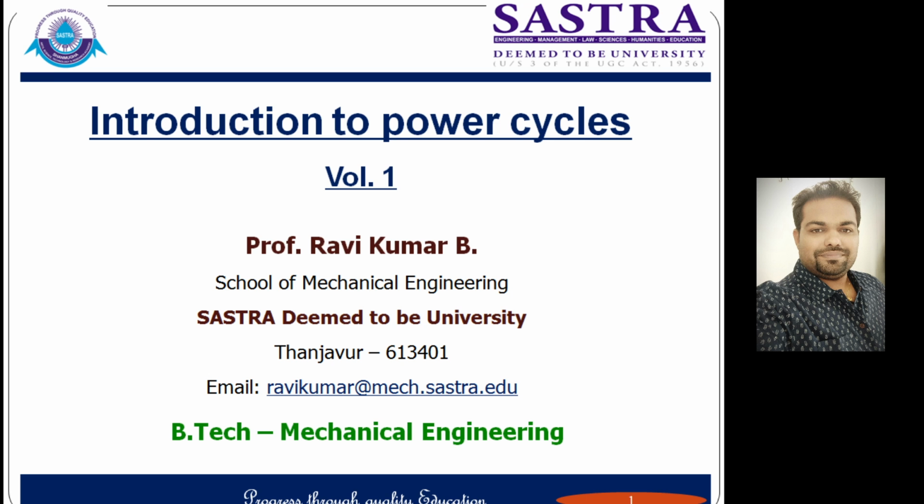The second type of power cycles is based on air. They utilize air as an oxidizer to carry out the combustion, and that high temperature hot gas combustion product displaces the piston. The piston is connected to the crankshaft, and the crankshaft rotates and you get the mechanical work output, in the case of the internal combustion engine. The second category is called the gas power cycle, where you generate the gas by burning the fuel in the presence of oxygen.